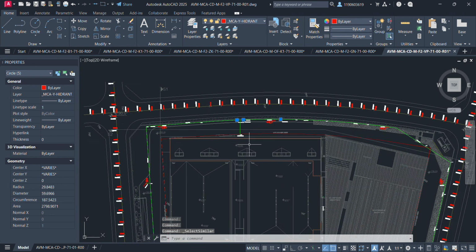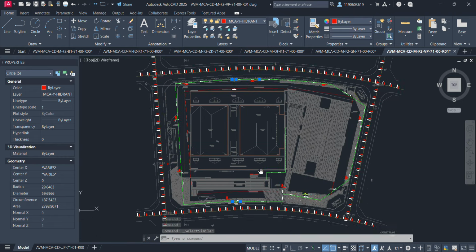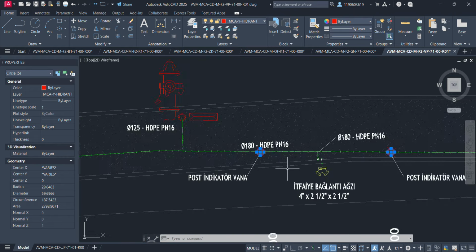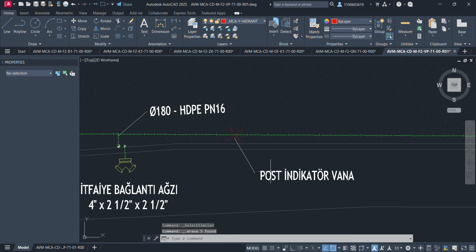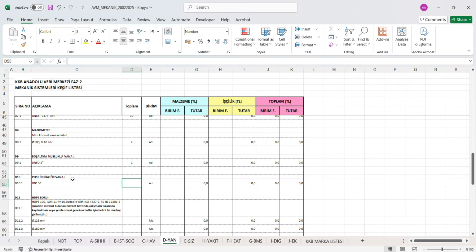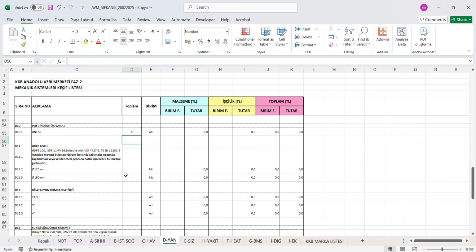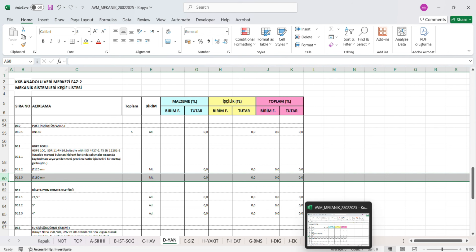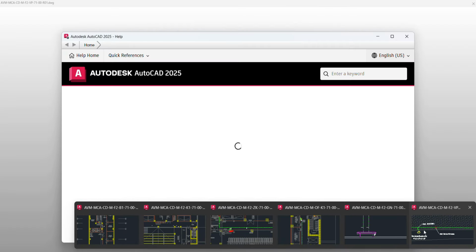Fire tank maintenance. To ensure the effectiveness of a fire tank, regular maintenance should be performed. This includes checking the water levels and ensuring there is no contamination. Testing the pumps to ensure the tank operates well under the required pressure. Inspecting pipes and connections to ensure no leaks are present.